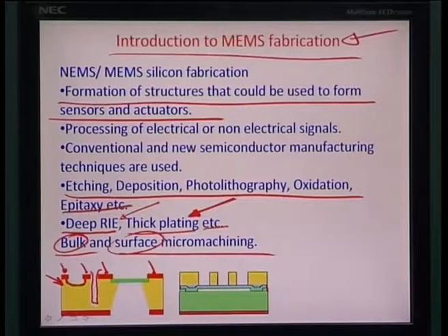You have opened an etch window at the top here in order to accomplish this, and this is a plasma driven process, and we are going to cover details of what plasma is in this particular topic or section in a few slides from now. This is another very interesting illustration. You are talking about depositing a P plus layer here. So this is P plus silicon in green, and you have opened another etch window, and then you etch the material in the bulk manner outside, so that you can realize this freestanding membrane like a flat beam, okay. So therefore these are really bulk micromachining processes, where it is a subtractive method, it is removed from the volume of the material. The surface, on the other hand, is an additive process, okay.